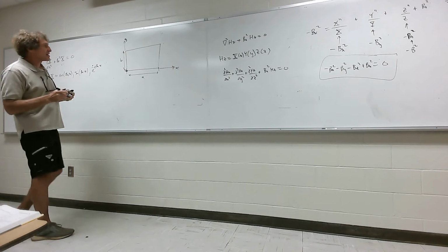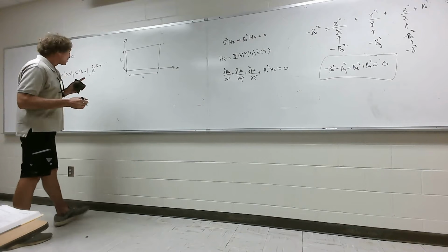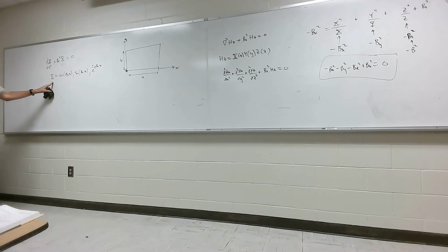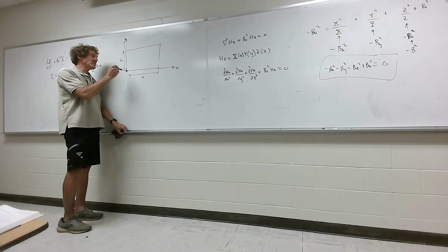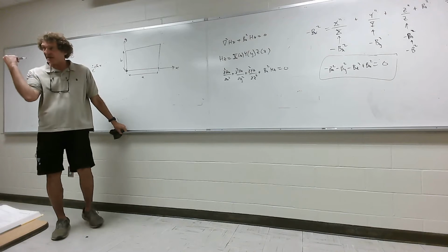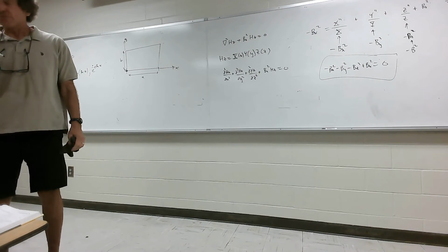All right, so coming back to this thing, now, we're solving for this. Remember, this is the form that the H field takes. Now, before when we did this, we knew one thing. We knew that the tangent value of the E field was zero on those things. In other words, Ez was zero, so that solution in X had to be zero at those boundaries. Do y'all remember that? At the four boundaries.